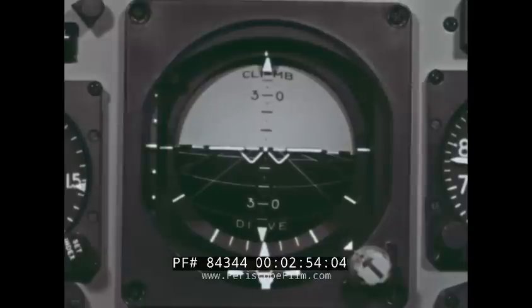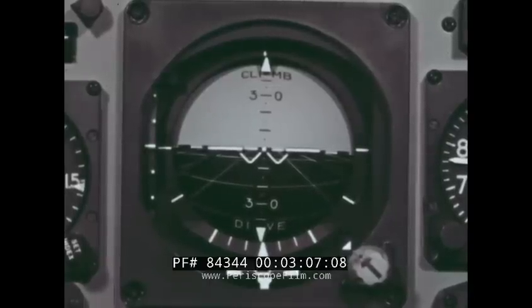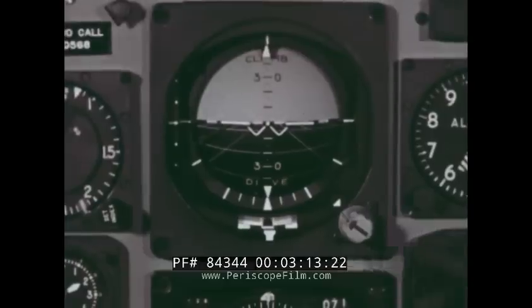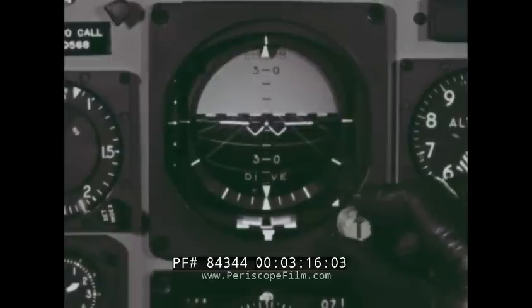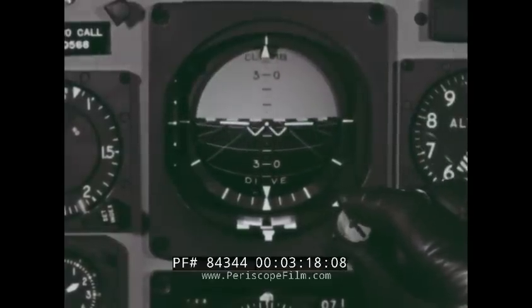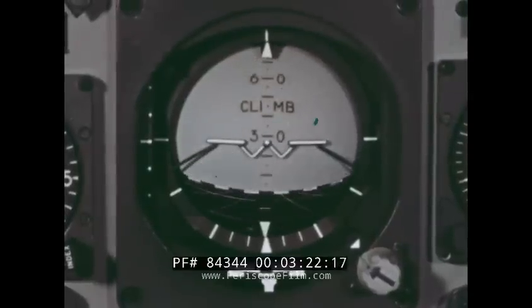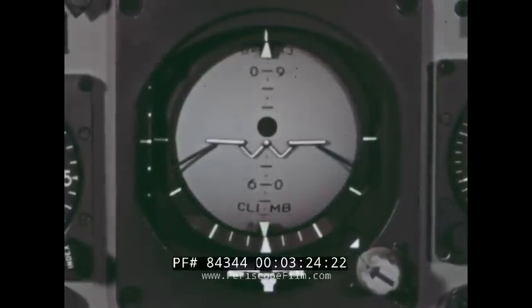The attitude sphere and the miniature aircraft make up the attitude indicator function of this instrument. It is used almost exactly as the attitude indicator in the T-37, with some improvements. The attitude sphere is conveniently marked off in degrees above and below the level flight attitude. It is adjustable rather than the miniature aircraft, and the sphere rotates through 360 degrees of pitch or roll.